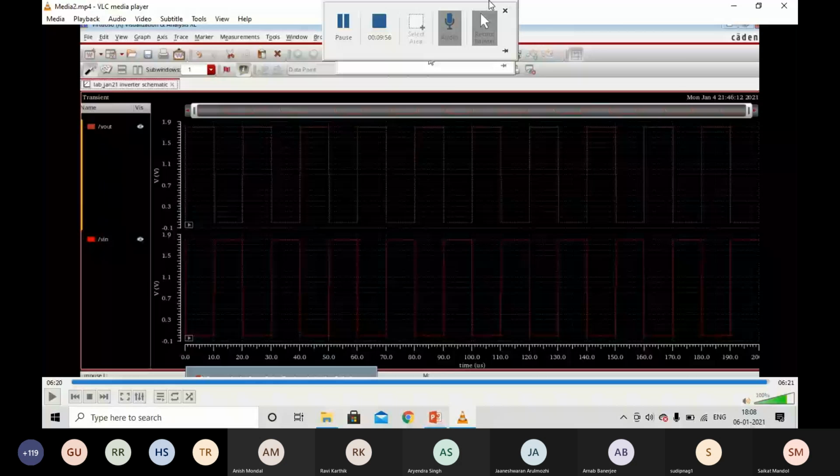So if you draw 2 transistors side by side in layout, you'll find 2 different sizes based on their selection of parameters. And secondly, in addition, those connections like VDD connection, input connection, output connection are also done through metal traces, some metal tracks. Layout means basically how do you arrange those tracks, how do you arrange the transistors and connect them between each other.